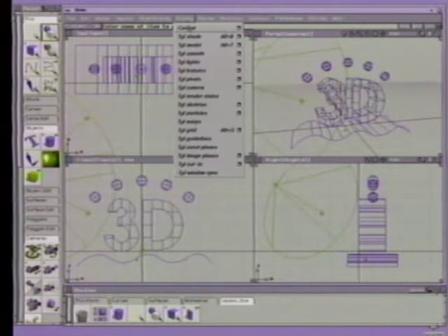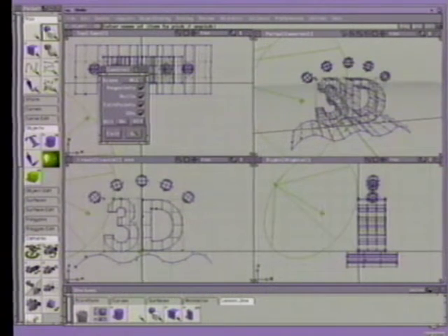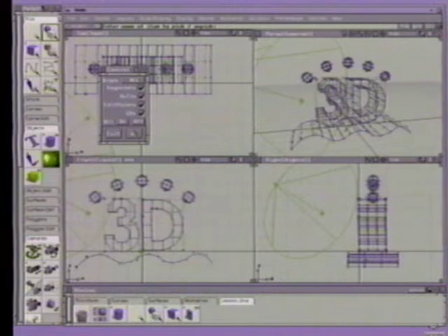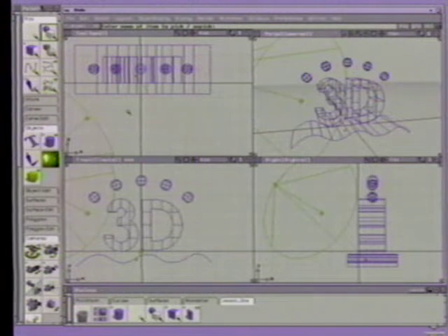From the display menu, select the control options. In the control window, set the scope to all and click on the All On button. Click Go. Now all the objects in the scene display CVs, hulls, edit points, and key points. You'll learn what these controls are in upcoming lessons as you use them to edit the surfaces of objects. In the control window, click All Off, then click Go. Close the control window. The controls have now been turned off.